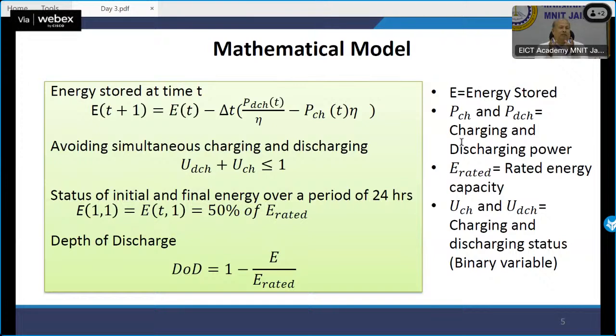So that is how the efficiency, or the charging and discharging losses, are being taken care of. So when you discharge, you divide by eta, and when you charge, you multiply by eta. All right. So that means what the battery will see within it during charging and during discharging. This is power after the converter. Yes. All right. So this is one equation I'm very sure that you all have understood.